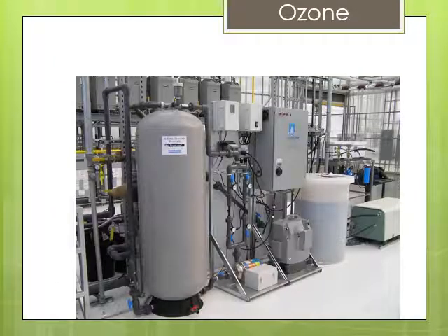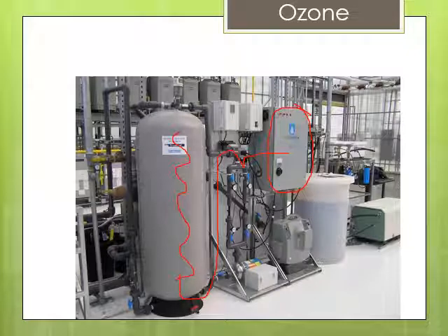So, moving on to ozone. Ozone is a very effective sterilizer. I used this in our lettuce at our greenhouse. This is actually similar to one we had. There's a generator in here that produces ozone, and it bubbles it through the water, so the gas is injected, and the water with the gas injected goes through a contact tank. In this tank, the water slowly moves up through the tank and then moves out to go into your greenhouse for irrigation. And the gas that's collected at the top accumulates at a little charcoal filter.